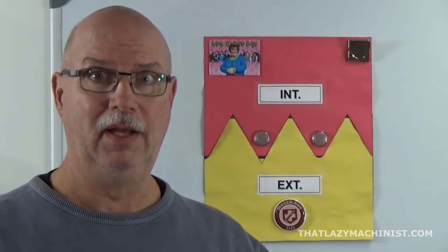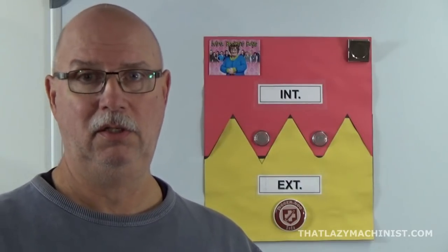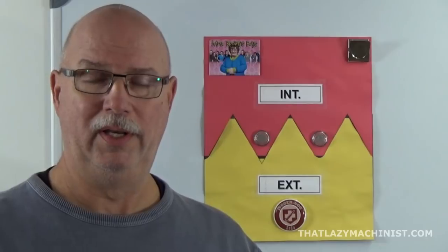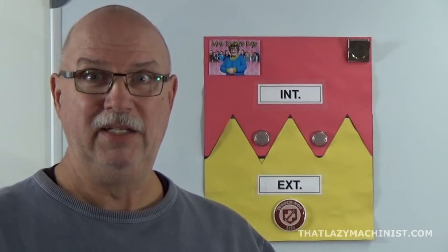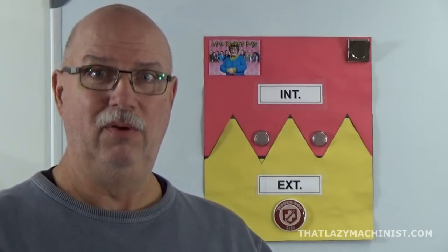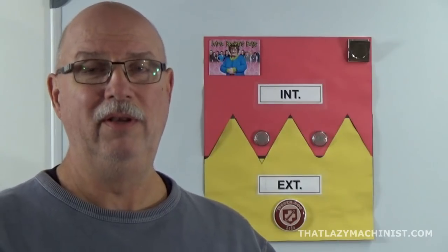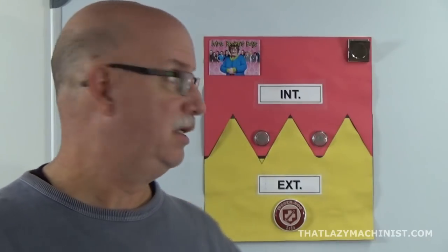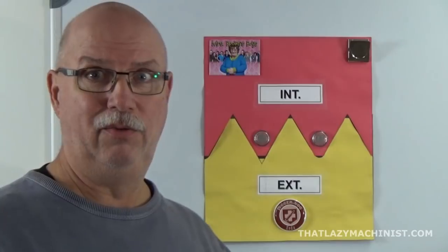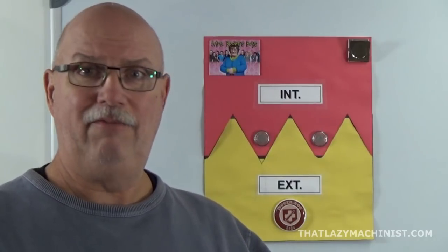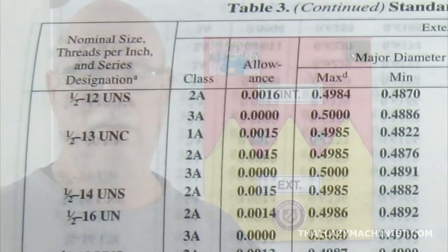Its nominal diameter is 1 inch. But it doesn't measure 1 inch, because a 1-inch thread that would thread into a 1-inch thread, well, wouldn't fit. We need space between the crests and the roots to have a thread that assembles together.